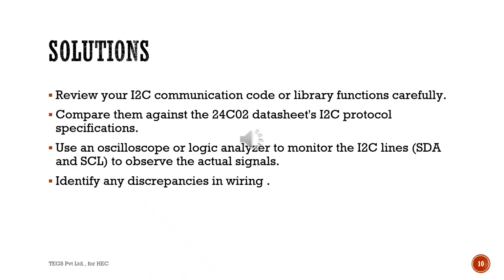Solution for troubleshooting. Review your I2C communication code or library function carefully. Compare them against the 24C02 datasheet I2C protocol and specification. Use an oscilloscope or logic analyzer to monitor the I2C lines, SDA and SCL, to observe the actual signal. Identify any discrepancies in wiring.